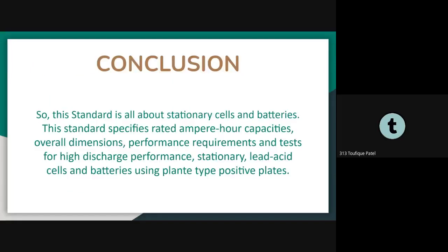So, conclusion. This standard is all about stationary cells and batteries. This standard specifies rated ampere hour capacities and overall dimensions, performance requirements, and tests for high discharge performance stationary lead acid cells and batteries using planté positive plates.